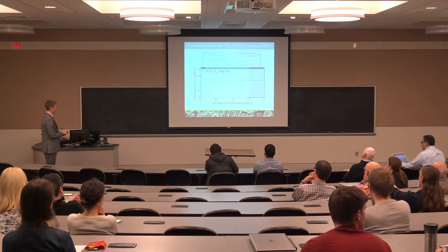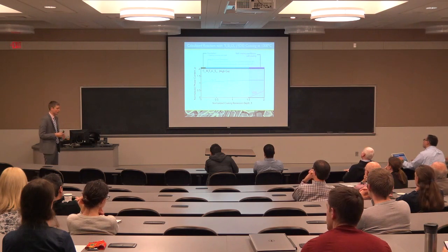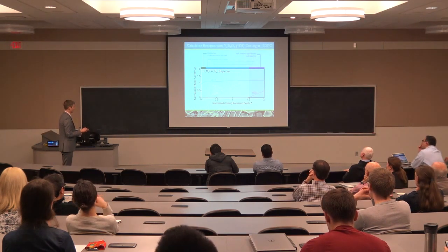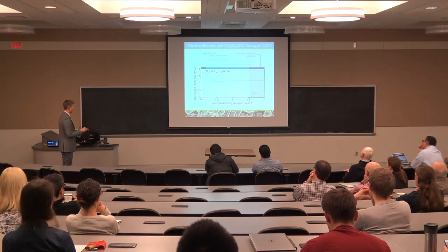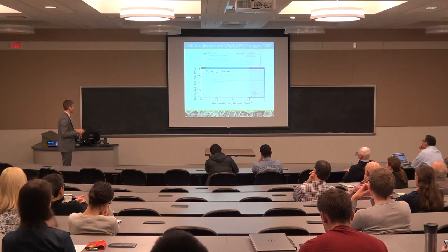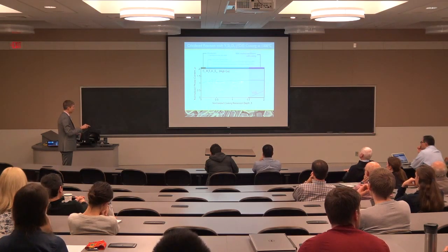Initially, if we have a small recession depth, the coating dissolves into the melt to saturate the melt with yttrium. As we increase the recession depth, now we see the apatite start to come out. When we look at the constitution, or the normalized phase content in that reaction layer, we see more and more apatite as the reaction proceeds. We're not really consuming the liquid at all.